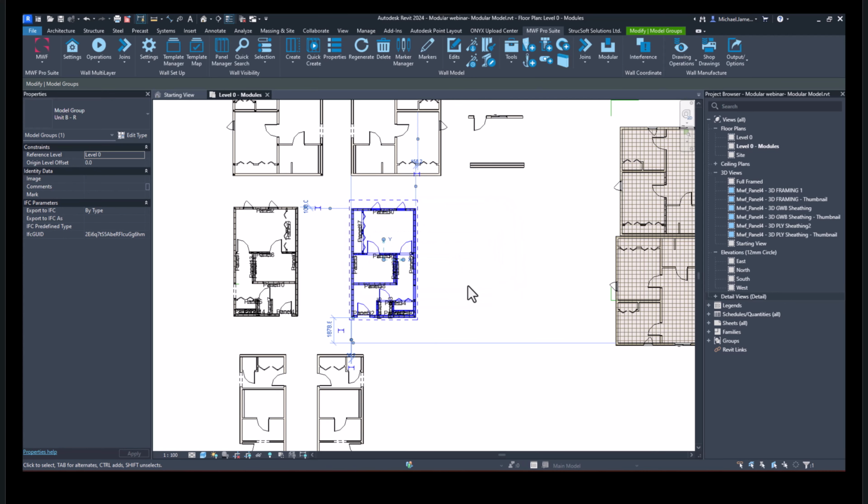What we need to do this time, rather than select the group first and distribute the settings from this group to all the other identical groups, what I can do now is I can click on the group that I want to frame. So this one, for example, go into the modular menu, and from there I can say copy members from group, where it's going to prompt me to select the group that I want to copy the properties from. I'm just going to select this group here, and again we have the same menu that we've just seen not too long ago. So from there I'm going to unlock the panels this time, and I'm just going to click OK.